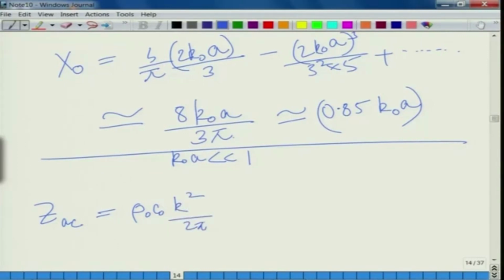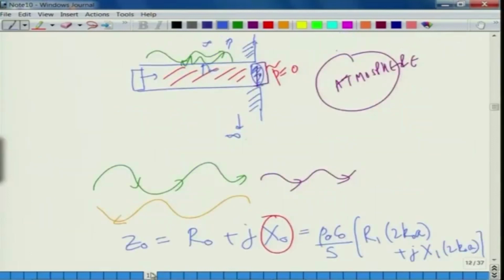So, we are trying to simplify things, and plus j omega times rho naught S by S squared into 8a by 3 pi. This of course follows from certain simplification. You have your 8a and 3 pi clubbed together, k naught I have taken and actually put omega by c naught, and some simplifications were done to finally arrive at the actual impedance seen by the wave here.